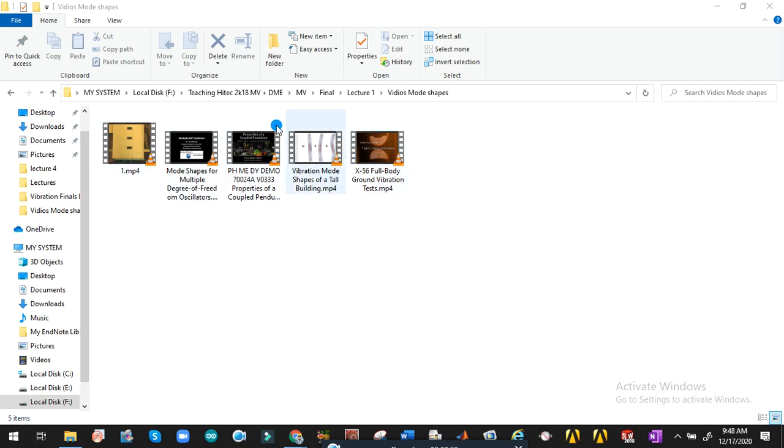Okay, I am understanding. Look here, please. In case of earthquake, you people know that if we have a tall building of about 15 to 16 floors, you are talking that case. Okay, one of the example. So in that case, we have multiple degrees of freedom. Why? Because we have multiple masses. Because each floor will be considered as a mass, and columns will be providing a stiffness element. If you have a room, then you can consider that walls are a stiffness element and roof is your mass.